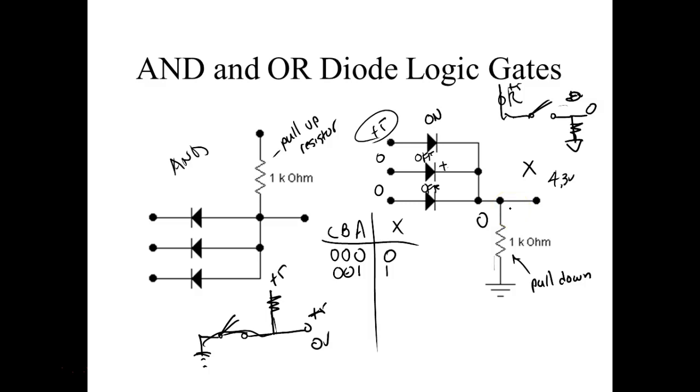But I'm making it go through what? A resistor. So as soon as I put that 5 volts on there, this guy's forward biased. It's only going to drop 0.7 of a volt, so my output would go to 4.3, and then this current right here would only be 4.3 milliamps, which is not much at all, right? You understand?